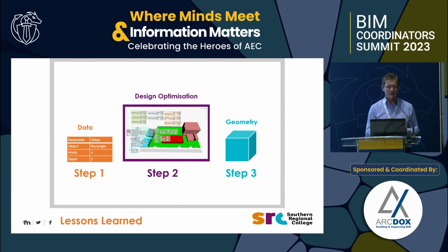So what they're doing is they're giving over information with more tolerance, for example. So you're not saying, here is our schedule of accommodation from the business case. What you would be saying to them is, here is our actual space register with an adjacency matrix, and then on top of that, we're going to give you minimum critical space dimensions as well as maximum tolerances.